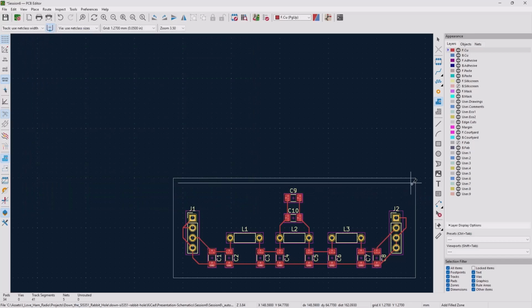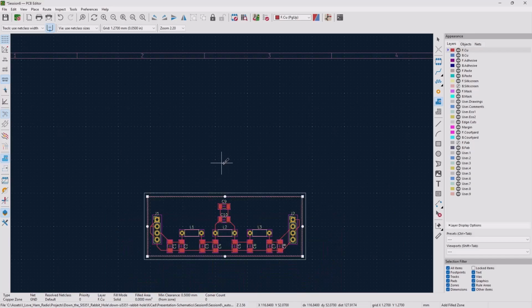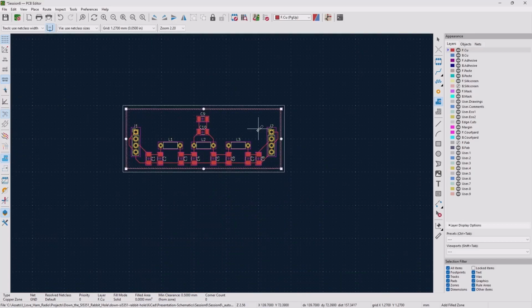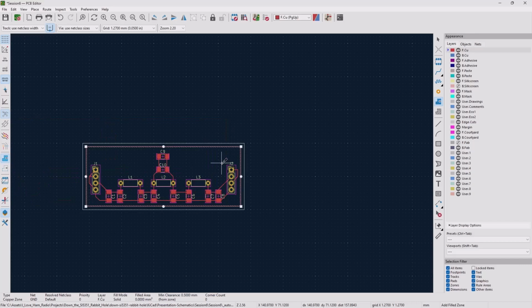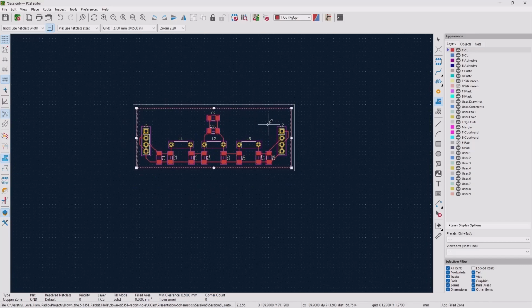What I'm doing now is I'm going to draw a square around everything, and we're going to create what's called a ground plane. So everything in here is going to be a ground plane, and so when it actually defines it and does the printout, all the grounds are going to be connected together. So that's why I wasn't too worried about these pins here and how they looked, because they're all going to end up being brought into that. Okay, so that's good there.